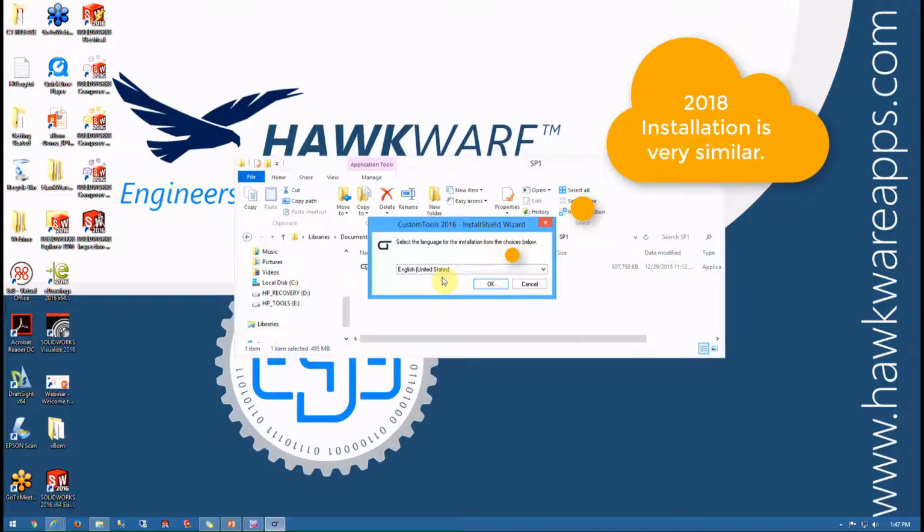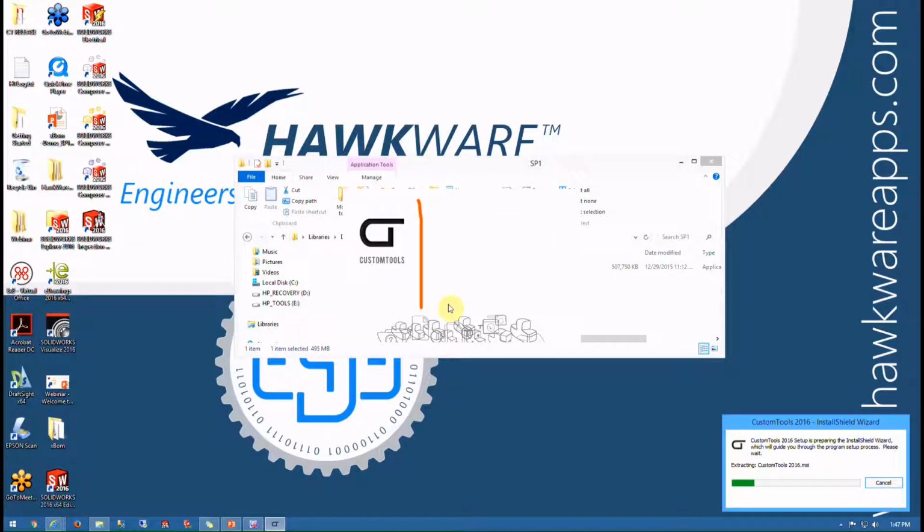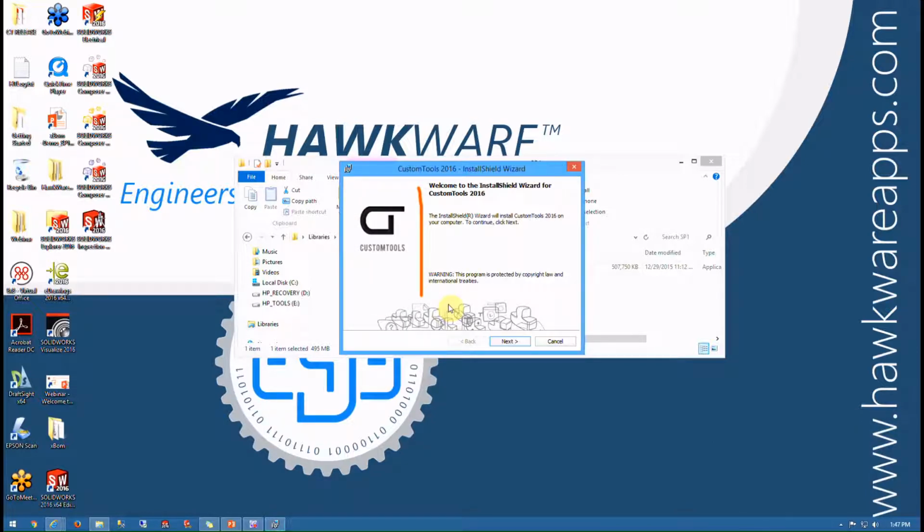Now, since I'm an Enterprise PDM, SOLIDWORKS PDM Professional user, I'm going to leverage the SQL server that I already have. So that part of my installation might be a little bit different than yours. You don't have to use the same SQL server. It's a completely separate product, so it's just all based on licensing for your SQL at your facility.